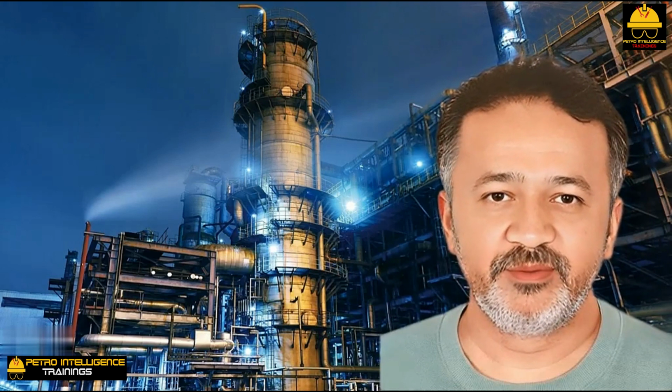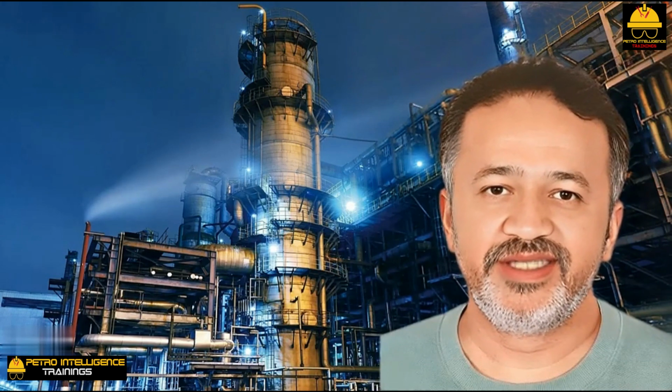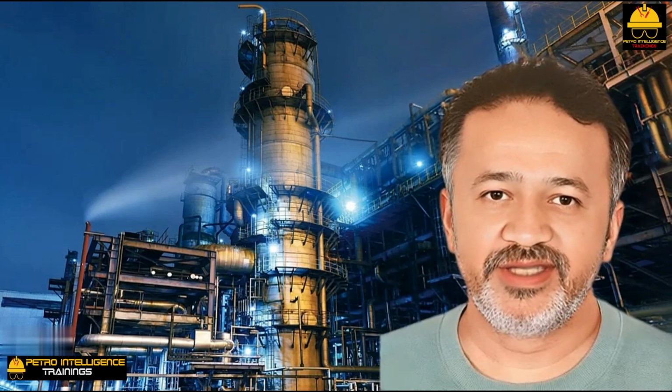In order to make this diffusion possible, there must be a concentration gradient with a higher non-condensable concentration near the tube surface, which then impedes the condensation rate of the bulk of the vapor flow. You can see this in Process Instrumentation, Institution of Mechanical Engineers, Volume 178, page 351, 1963 to 1964 edition. This explains why venting a small amount of non-condensables often has the dramatic effect of increasing condensation rates, especially when condensing pure components such as steam.